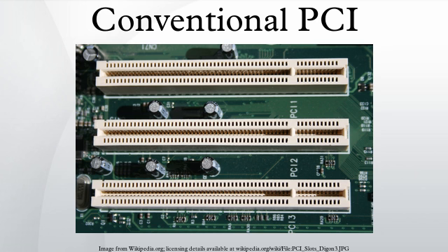The mapping of PCI interrupt lines onto system interrupt lines, through the PCI host bridge, is implementation dependent. Platform-specific BIOS code is meant to know this, and set the interrupt line field in each device's configuration space indicating which IRQ it is connected to. PCI interrupt lines are level-triggered. This was chosen over edge triggering in order to gain an advantage when servicing a shared interrupt line, and for robustness: edge-triggered interrupts are easy to miss.